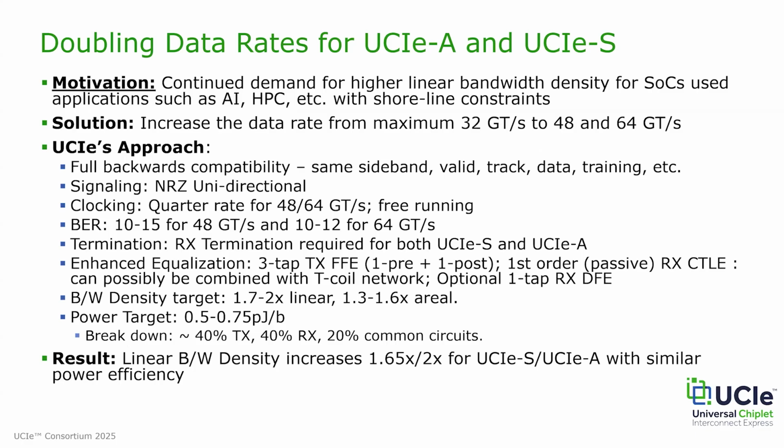So there is an insatiable demand for high bandwidth in applications like AI, HPC, and data analytics, and the die sizes continue to be constant, right? The way to address growing bandwidth demand is to double the frequency as long as we are, again, bump limited and our power consumption is constrained. And the other way is, of course, to reduce the bump pitches like we talked about.